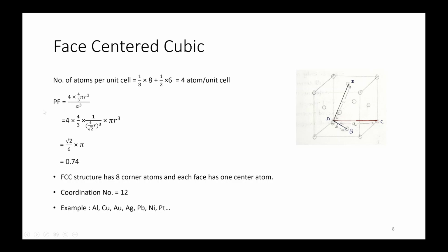And for finding out your packing fraction, in this case, a will be equal to 4 upon root 2 times R. So packing fraction will be 74%. It is the highest, along with HCP.